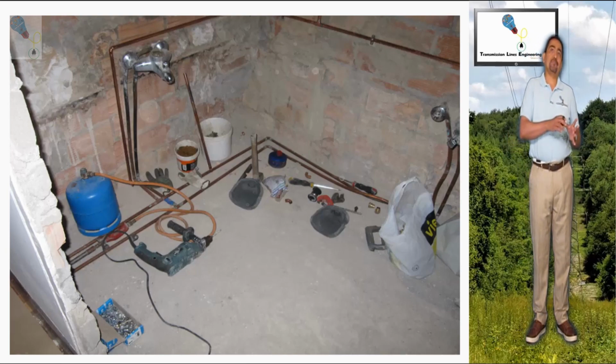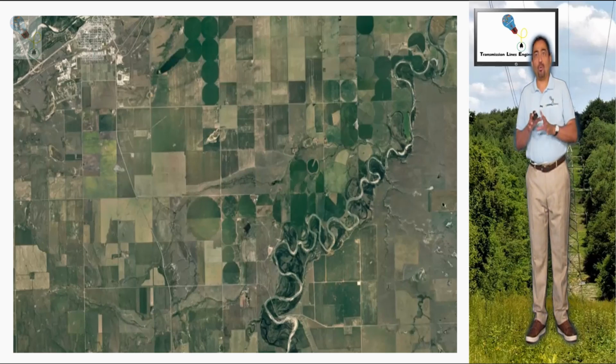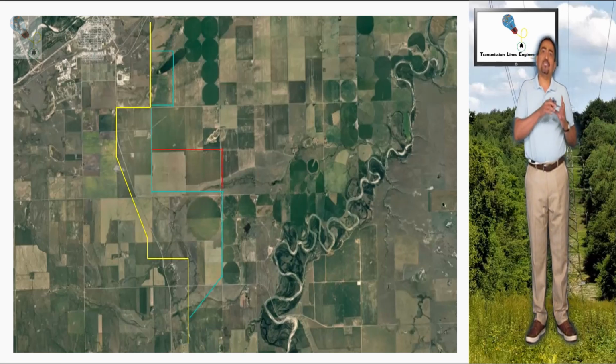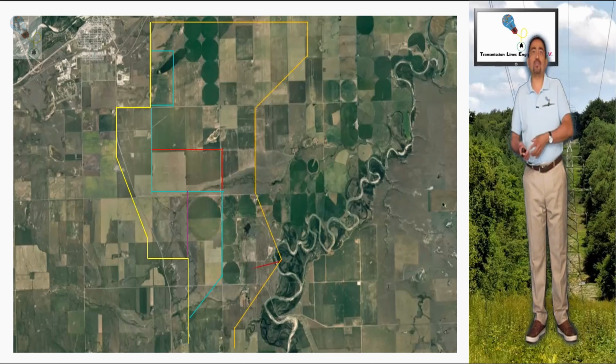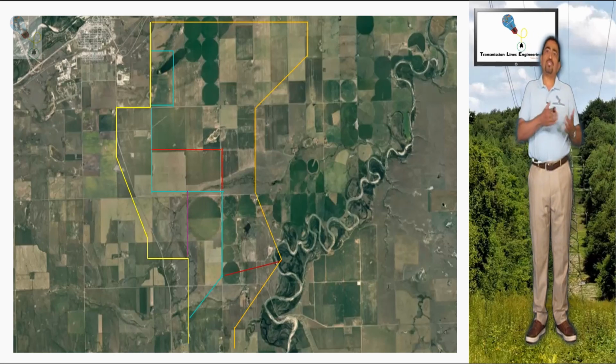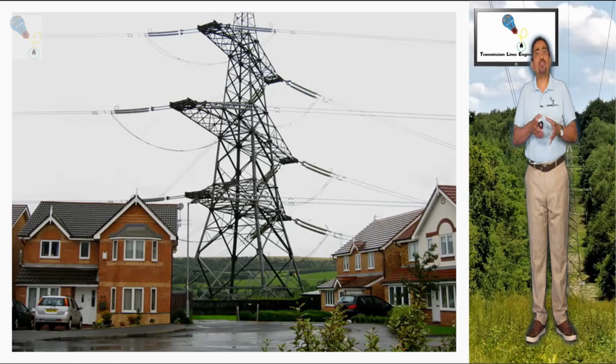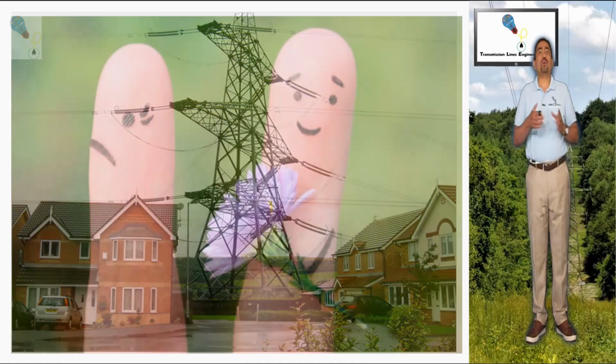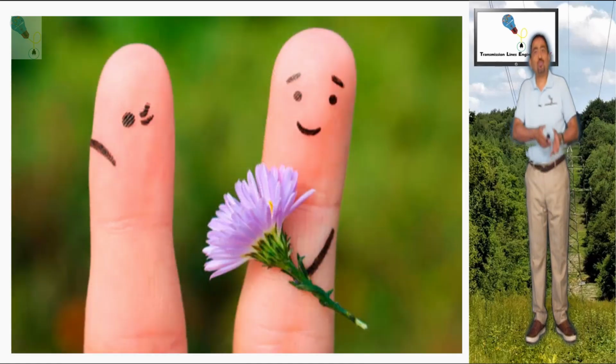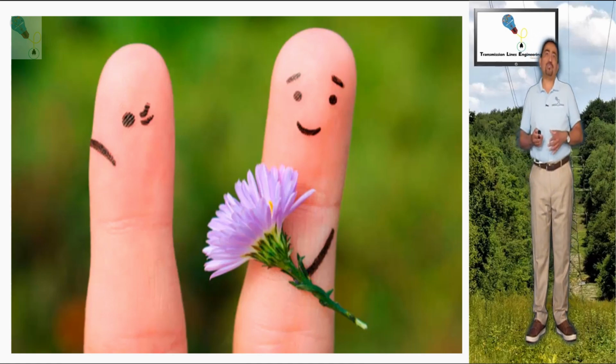Step number three, having the bidding rules or the DBM, the contractor will proceed to perform the detailed engineering, starting with the structure locations throughout the different alignments requested by the client. Once the structures are spotted on the paper, the client will contact the landowners where the structures are going to be located to request their authorization to erect the structures in question.